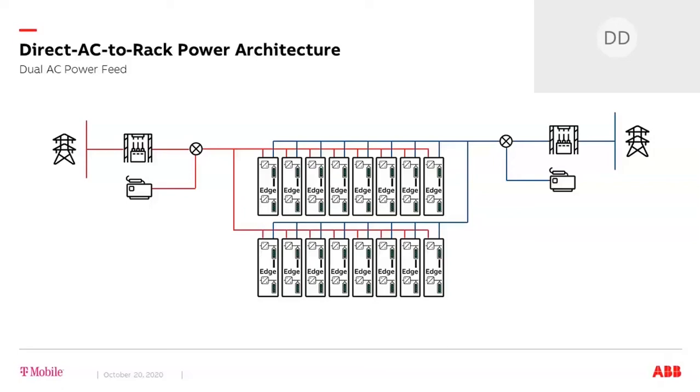So in fact, you have a full dual redundant powertrain with backup power sources in each path, 4 independent AC sources, each capable of supplying the entire facility. And 2 utility feeds have to fail before the battery is ever going to go on discharge, and even then, only for the time that it takes for one of the 2 generators to start.